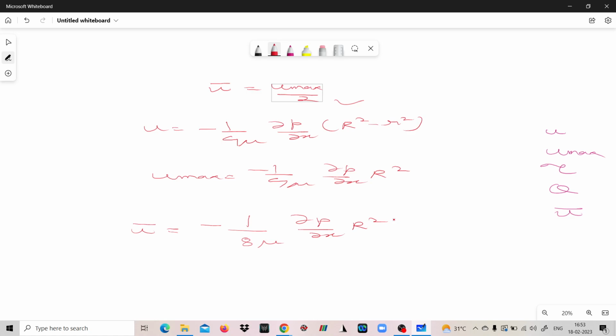Now what will be minus of del P? Minus of del P will be 8 mu U average by R square into delta X. Okay.